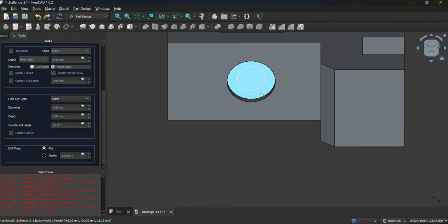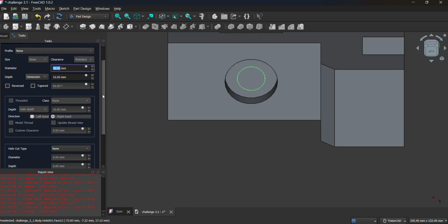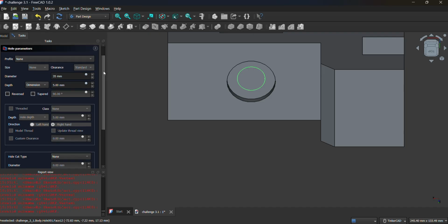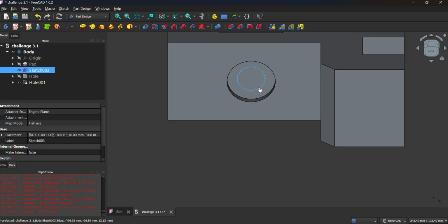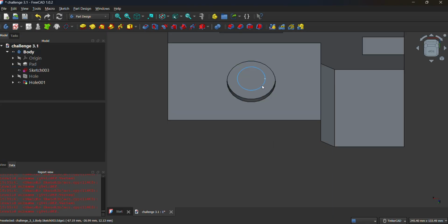Okay. There's an existing sketch because I repeated this already, but there's no need for this anymore. You can draw another circle. Let's click OK first. Must be 5. Be careful as you scroll, just like what happened a while ago. When you scroll your mouse here, it will change the value of your diameter and depth. So always review it, then click OK. Again, there's a circle sketch here because I already repeated this one because I thought it was recording, but it was not. So I'll just remove this one because there's no need for that.